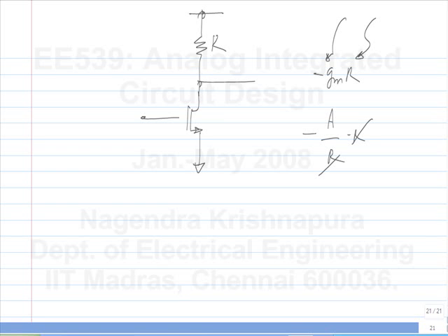There is no feedback in this circuit. It's still GM R, but somehow you have adjusted the GM to vary inversely proportionally to R. Okay. So similar thing for the bipolar also there, except one more. It's also a little more useful because you know the exact temperature dependence. Okay. So you can use it as a thermometer, for instance. You somehow use that circuit and then you get the current or some voltage out and you get something proportional to the absolute temperature. So that's a thermometer.